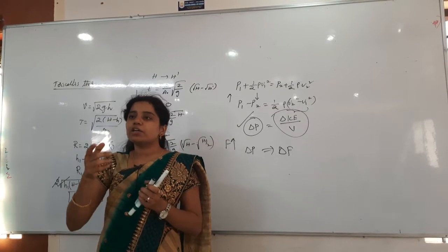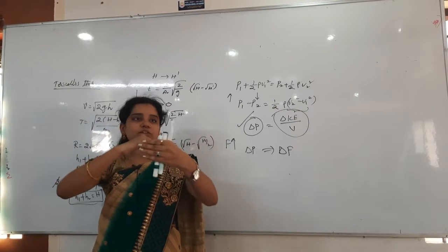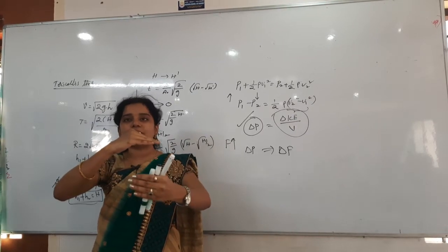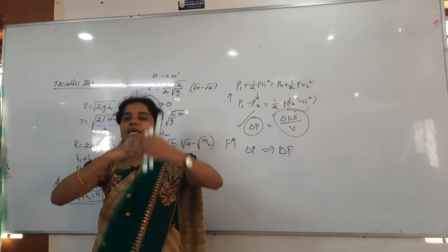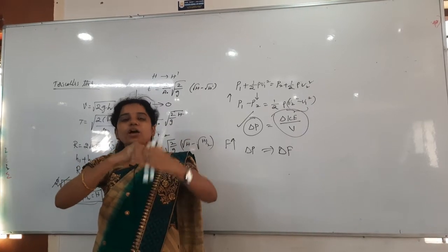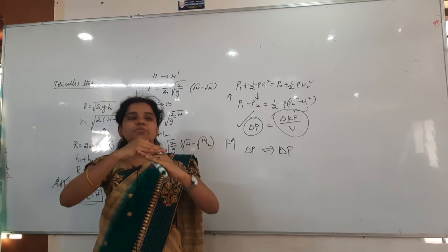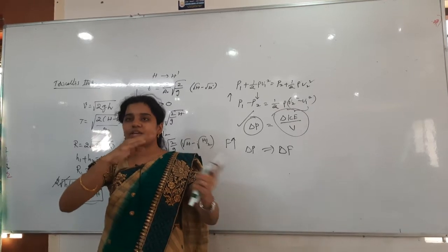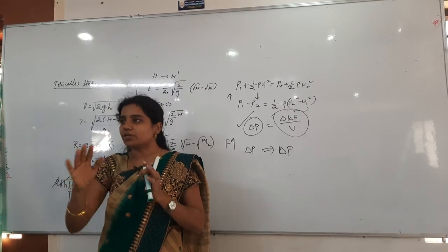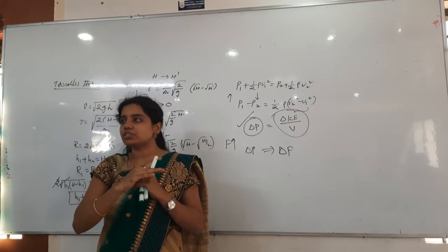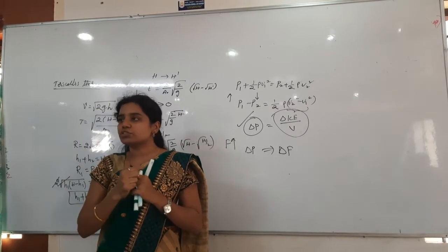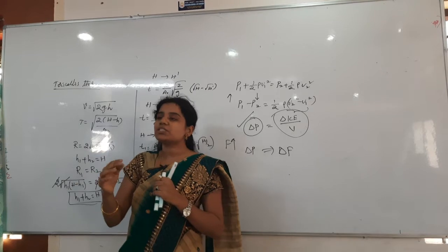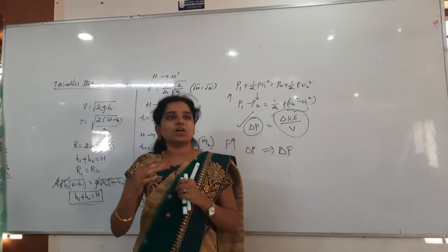In case of the aeroplane wing, we have seen the aeroplane wing like this. Top surface was there, curved surface, bottom surface was depressed. So due to that depression what happens? Nothing but air at the bottom surface will be less as compared to the top surface. So only on the top surface velocity is more, on the bottom surface velocity is less. This velocity difference creates you the pressure difference. Where that is more, where that is less, you just forget about that. The velocity difference is creating the pressure difference. That pressure difference causes the thrust force. So net force is not equal to 0. If net force is not equal to 0, the body is not in equilibrium. That is about all the lift cases.